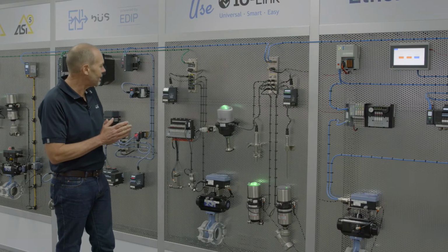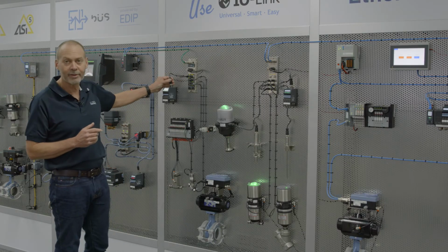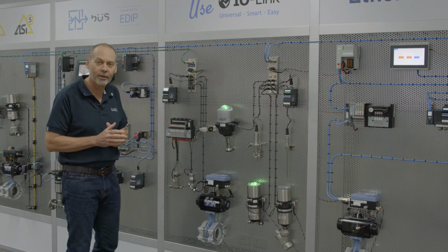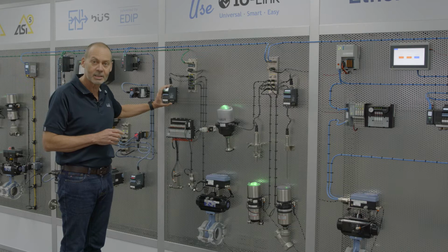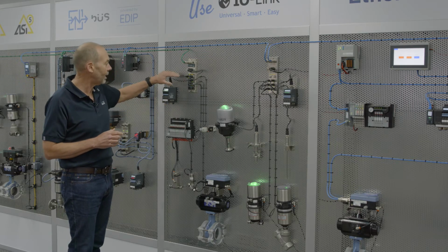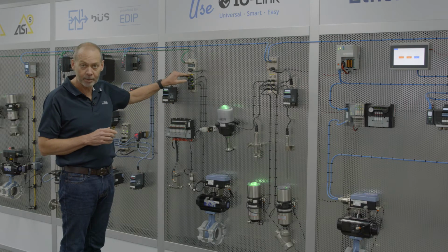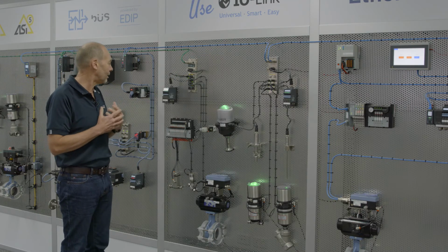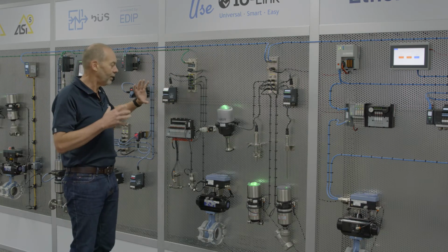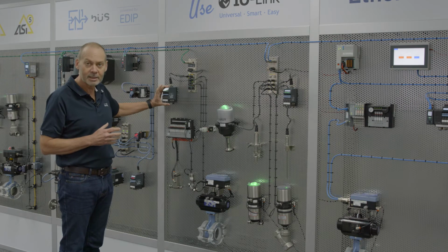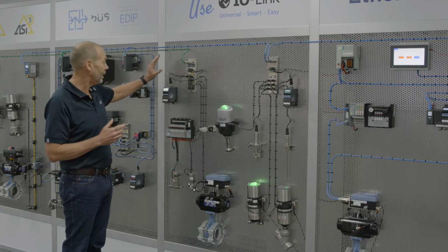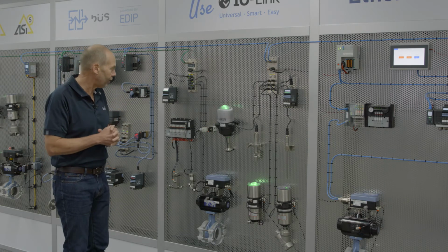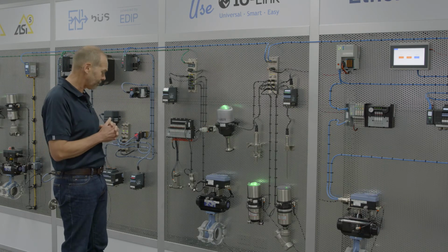The nice thing is IO-Link doesn't just control the valves, so we're not just saving wiring, but all of the asset management and diagnostic information of this device is also passed up to the IO-Link block. So you've got a complete footprint of everything in that device being communicated up into the IO-Link head, and that gives you a lot of functionality and a lot of features.